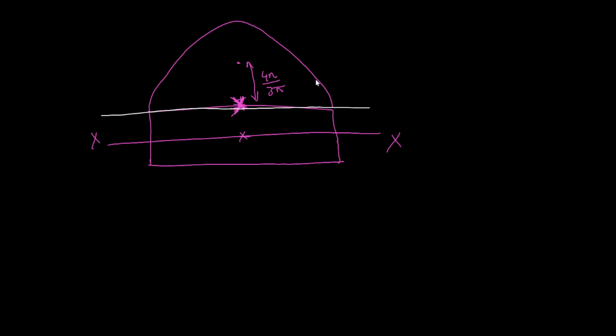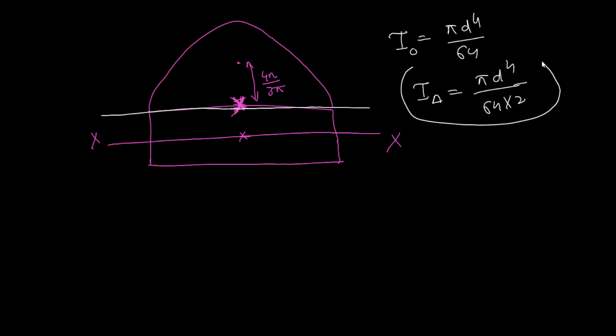How much will it be for the semicircle? For the circle, you know, it is pi d4 by 64 about the OO. So for the semicircle, it will be half of pi d4 by 64, so you will calculate about this axis. You got Ixx of the rectangle,